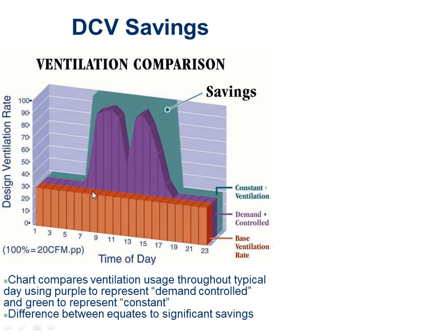In a CO2 system, when we're tracking the actual people that show up, we often find, surprise, surprise, that everybody doesn't show up to work every day. I know it's hard to believe. So we get this purple type profile. We call this a 2-hump profile because it's an office building. So people mostly come in on time, but a lot of them trickle in an hour or so late, or maybe they have different starting times, or maybe they had to go to a meeting beforehand, or who knows what.